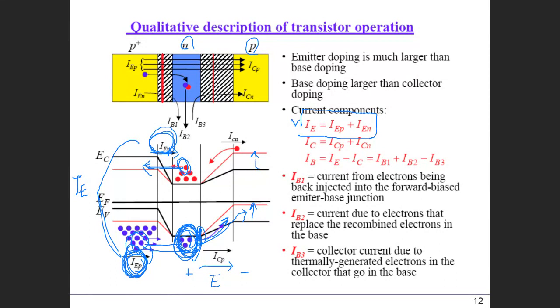When the hole is swept to the collector side, that hole contributes the so-called collector side hole current. Now, similarly, you have the minority carrier in the P side. So this electron, when it sees this high electric field region, can also sweep to the base region,